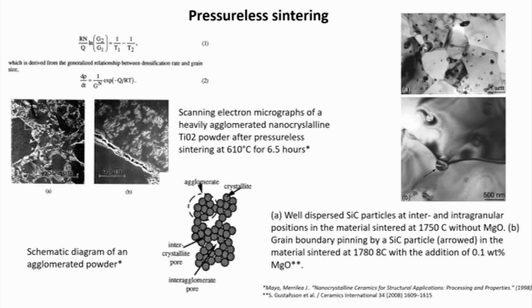For pressureless sintering, the presence of large interagglomerate pores in the nanoceramic powder compact is shown to be a root cause of high sintering temperature and slow densification rate. There is a strong dependence of densification rate on pore size, with smaller pores yielding faster densification rates, and higher densities at a given grain size can be achieved. In contrast, variation of ceramic sintering schedules is generally unproductive or counterproductive with respect to altering the density-grain size trajectory.